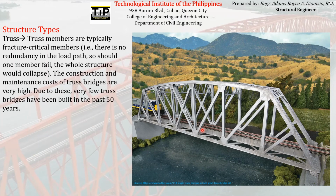Due to this critical maintenance, this results in a high maintenance cost, in addition to the high construction cost of truss bridges. Due to this high maintenance cost, very few of this type have been built in the past 50 years. So we don't usually build truss bridges nowadays due to the high maintenance costs.